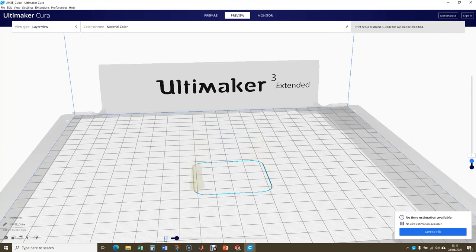So we actually see exactly how the 3D printer will print the individual features. This can be very useful if you print something on a 3D printer and it fails the first time. You can go back and see what order it should have printed in, where that corresponds to the way my printer failed, and you can maybe alter the order in which they're done.